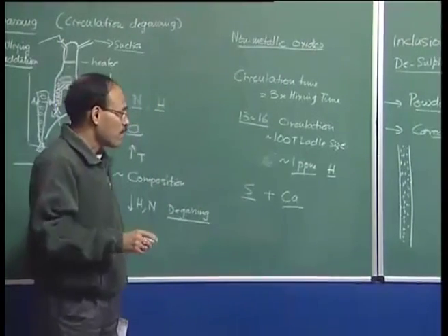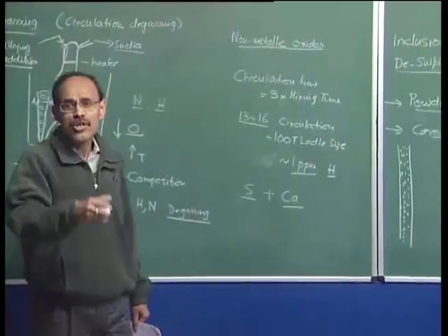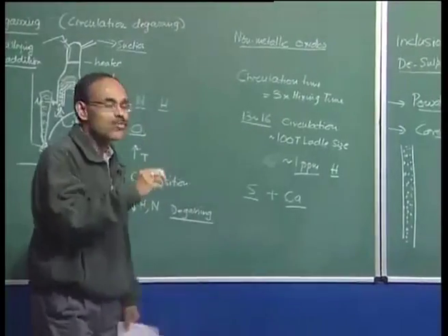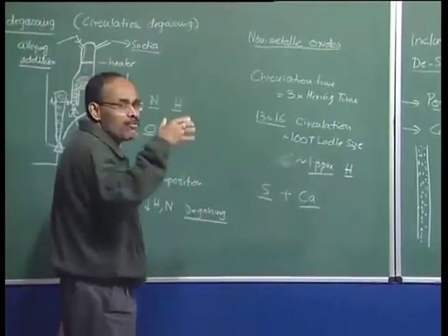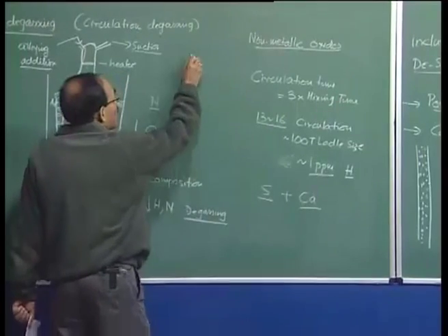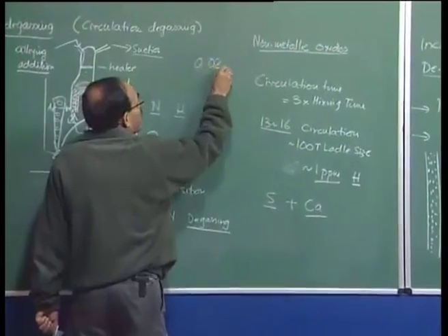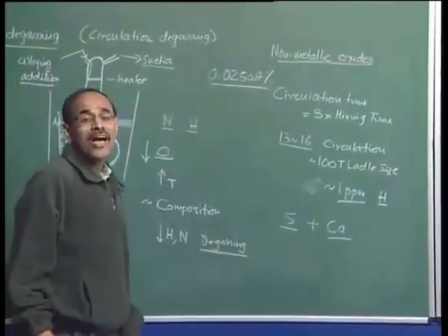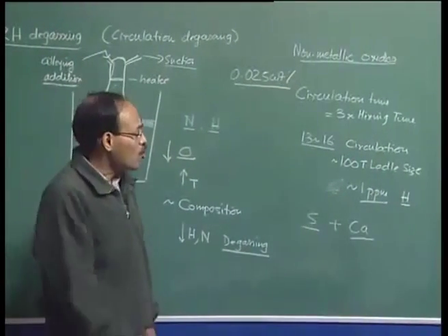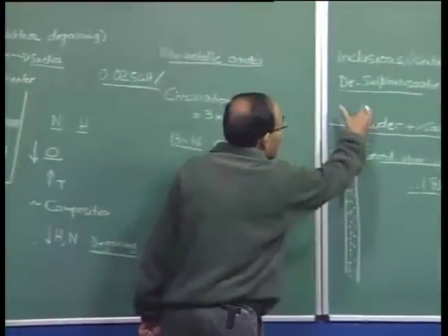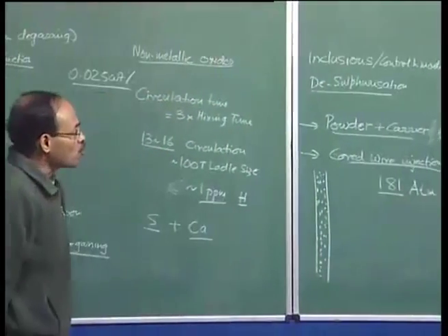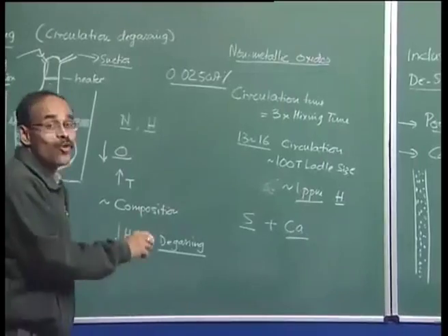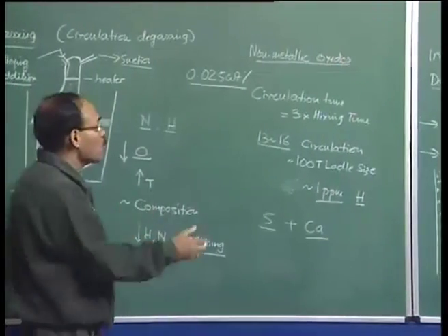And indeed, this is a very important issue in calcium injection, that the recovery of calcium is extremely small. Also, even if you can increase the contact time, the solubility of calcium in steel is roughly about 0.05 weight percent. As a result, under steelmaking conditions, although injection of calcium has many advantages in terms of inclusion morphology, control and modification, it is going to be a highly expensive affair, because the solubility is less.